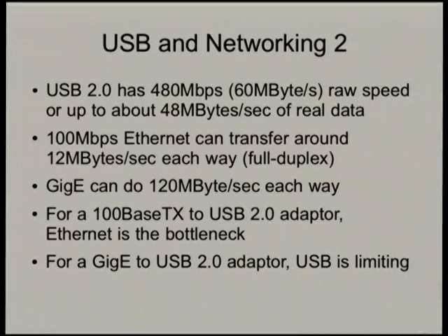The host is in control of all transfers, and it's not CSMA/CD, but strictly one device is signalling at a time. So the host controls who gets to talk on the bus at any particular time. So it's not full duplex. USB 2.0 signals at up to 480 megabits per second, or at lower speeds to be compatible with USB 1.1.